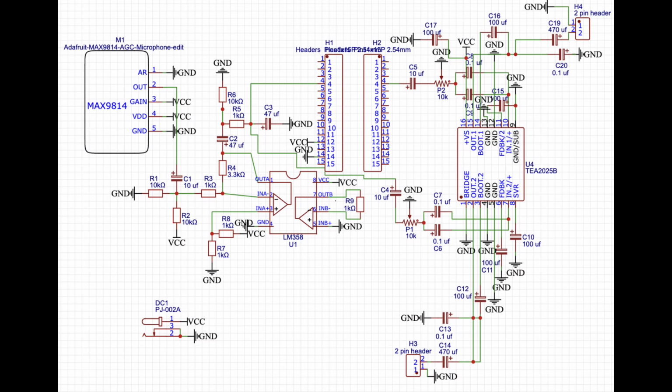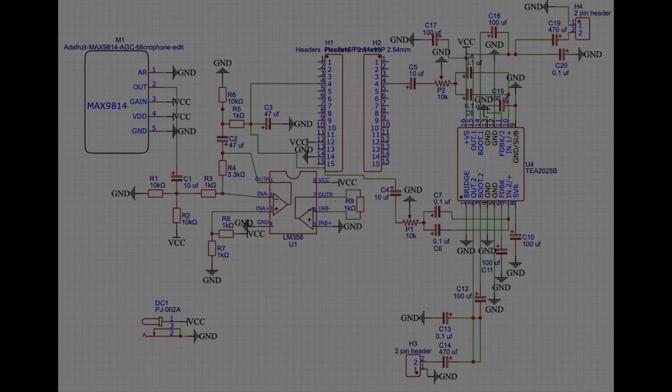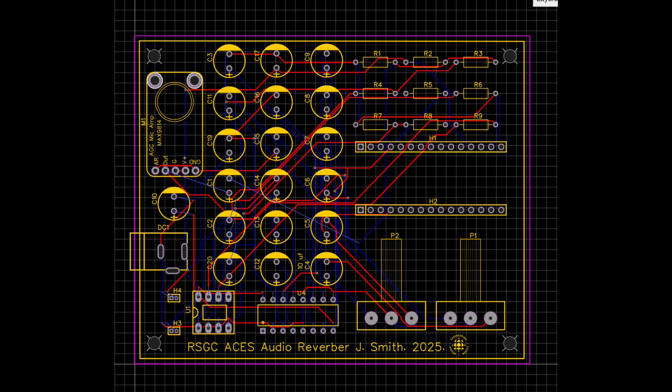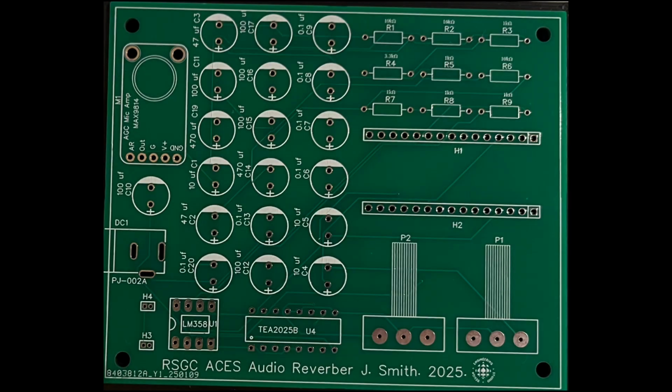The process of making this project permanent required a custom PCB. To start, create the schematic for the circuit following the prototype on EasyEDA, an online PCB design tool. Once the schematic is complete, convert it to PCB layout and arrange all the components in an efficient way. When done, auto-route the PCB. Then add final touches to the PCB, such as screw holes, your name, the date, and the circuit name. After ensuring all the parts are in place, generate the Gerber file for the PCB and use JLC PCB for fabrication.